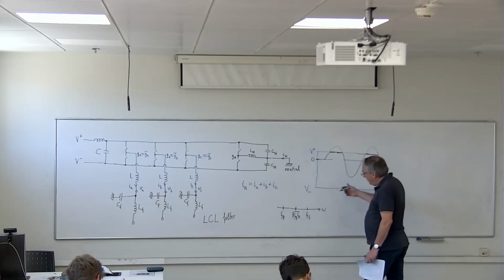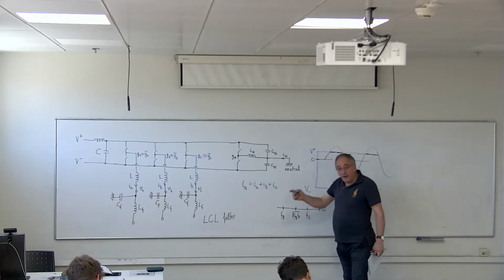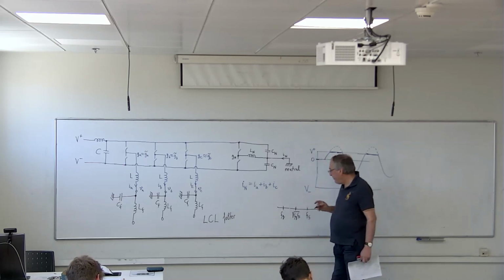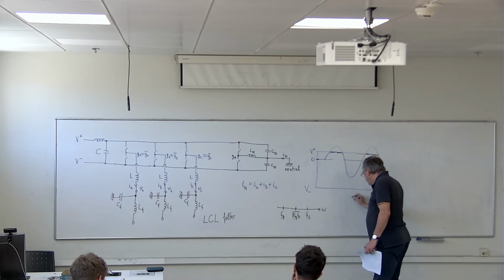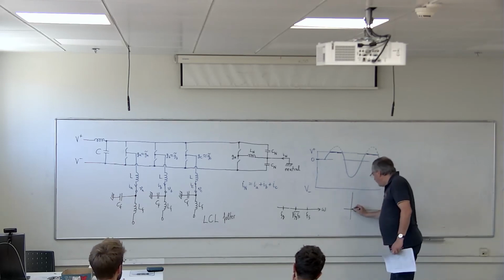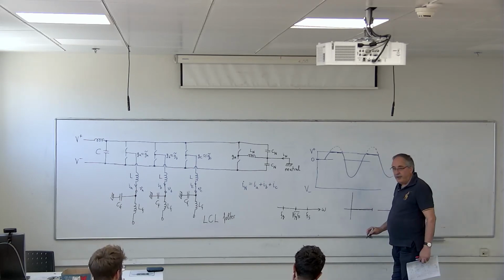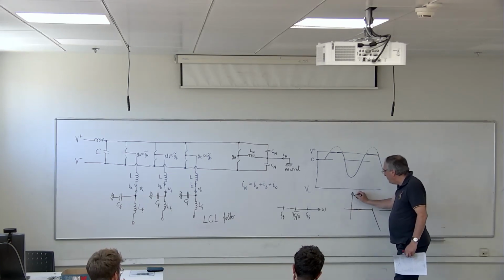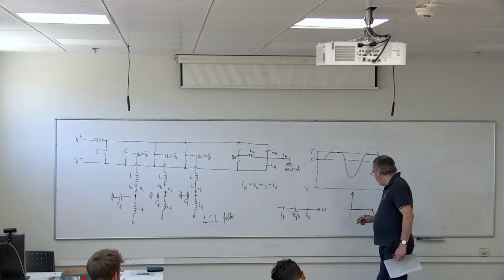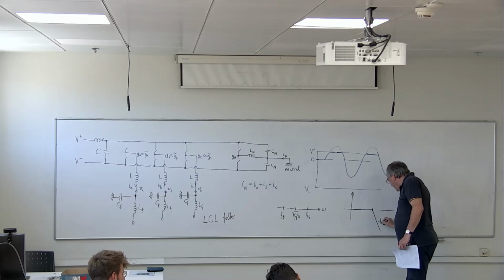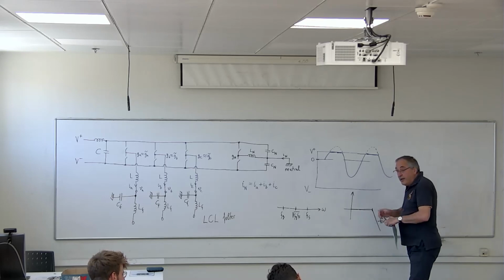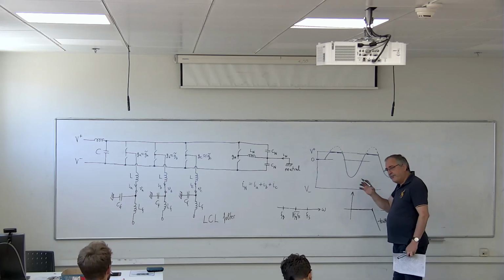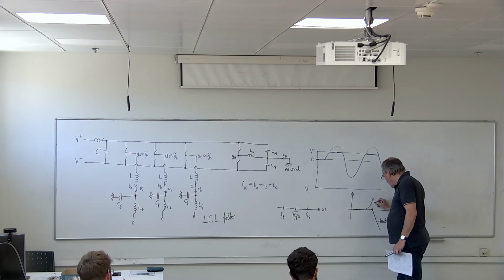And on the other hand, the switching frequency will also not excite it. So that's why you want it to be neither of the two. The picture is like this. Up to the resonant frequency, the filter will let every signal pass, and then it will go down. This is a Bode amplitude plot, output voltage against input voltage. At the resonant frequency, it will start going down at a slope of 40 dB per decade. Since there is no damping, there will be a high peak. Well, there is always some damping, but not big. So there will be a high peak here, like this.